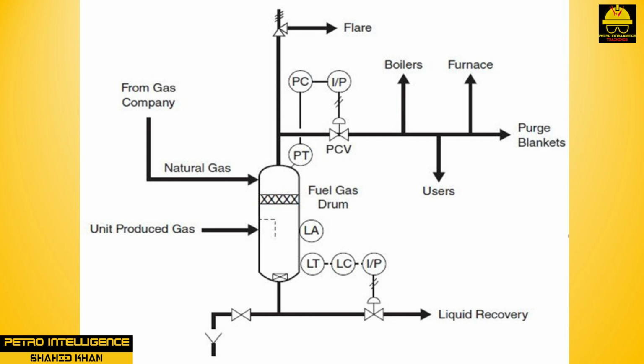The letdown/meter control valve is in operation at all times. A second valve opens when the flow rate is high and closes at low flow rates, thereby making possible more accurate metering of the gas flow. The plant natural gas distribution header normally runs around 200 to 250 psig. Each process unit has its own pressure control station that usually maintains the unit pressure between 60 and 100 psig.